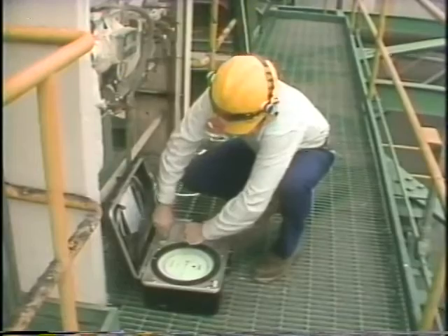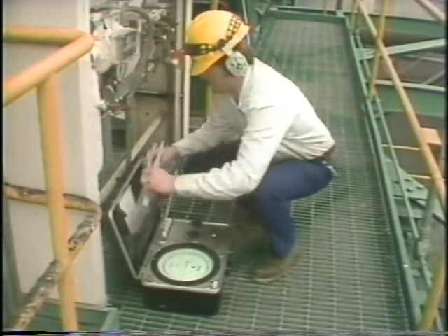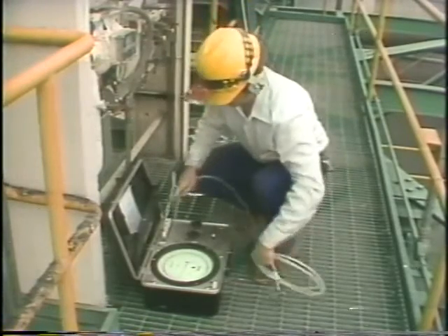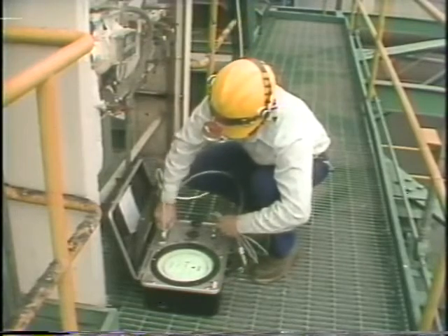If a visual inspection fails to turn up any obvious causes for the problem, you'll have to make some special tests. To test an instrument, you apply a known input to the instrument and check to see whether its output is correct or not. Each time you make a test, you'll be able to evaluate the results and compare them with the observations you've already made.